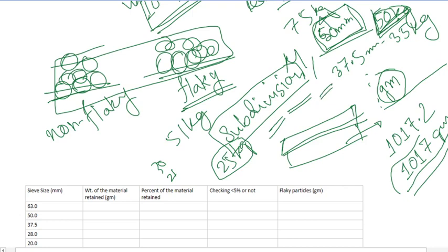The subdivision is specifically needed so that the sieve analysis we are doing is done in a proper way, so that, due to the amount of aggregates within that sieve, particles which are actually less than 50 millimeter are not failing to pass through it due to improper blending. So if it is greater than this size, a subdivision might give you a good value.